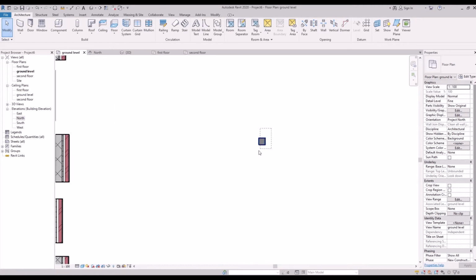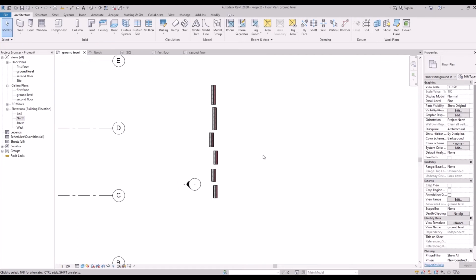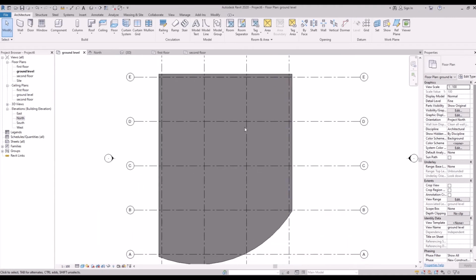That's fine. So when you're drawing, you can select the type that you want, from where you are entering the dimensions. Usually, as architects, we draw the dimensions from the center line. If you're working on interior drawings, usually we take the dimensions from the inside. So it depends on the project that you're working on.